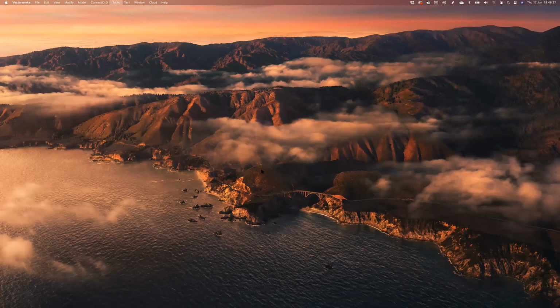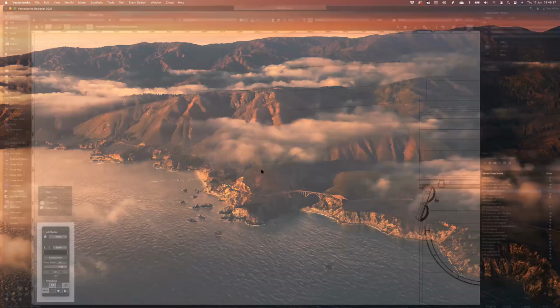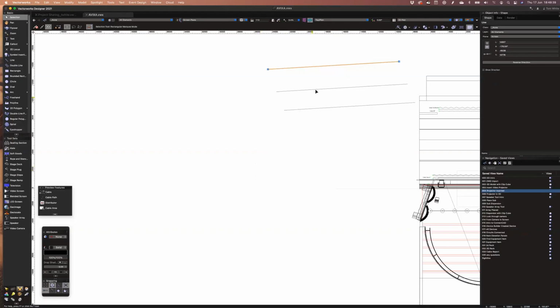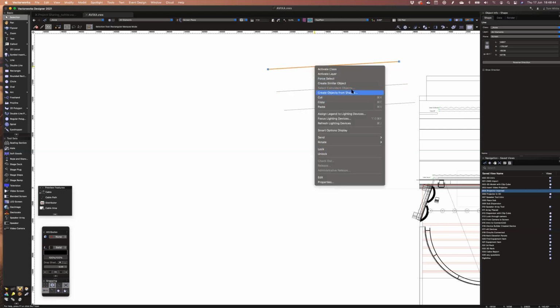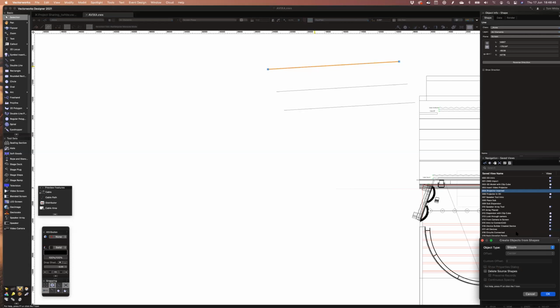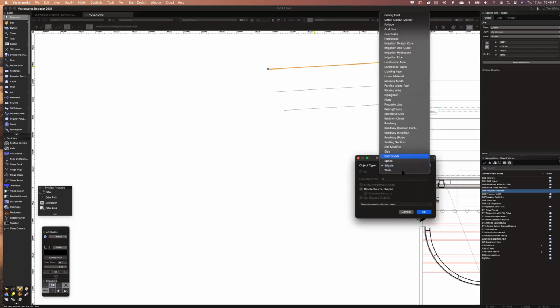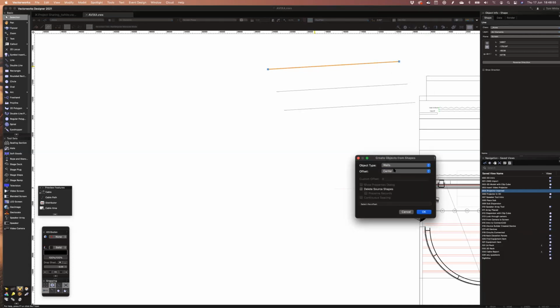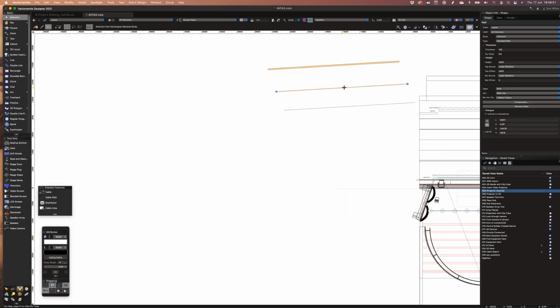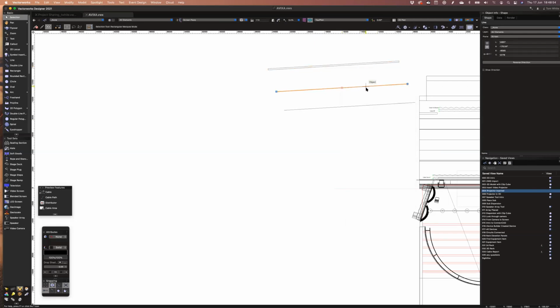select all of the squares in a drawing. They're supposed to be d&b E series speakers, but somebody's just drawn those rectangles. In Vectorworks there's a command where you can do convert, replace with symbol, and they just swap them all for speakers. So here in the Spotlight workspace, we have create objects from shapes. In this case, I can say let's make this a wall, for example. I'll leave it set to the standard settings for now and do create objects from shapes.